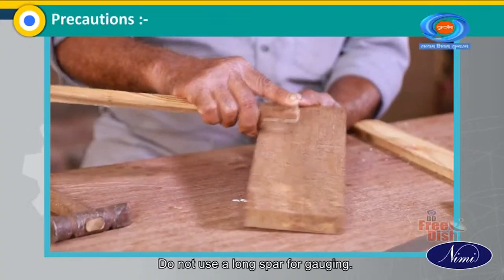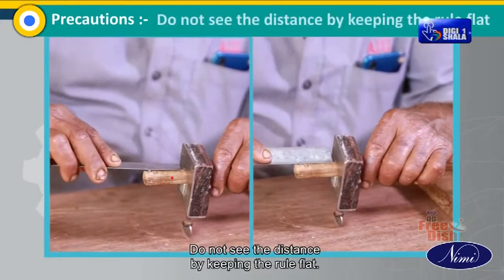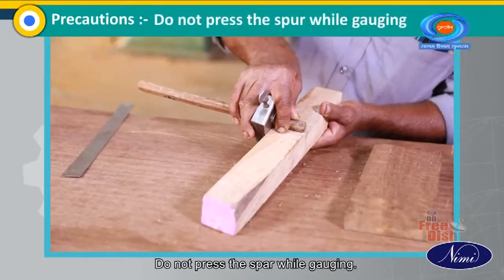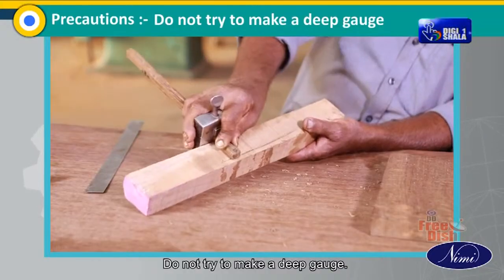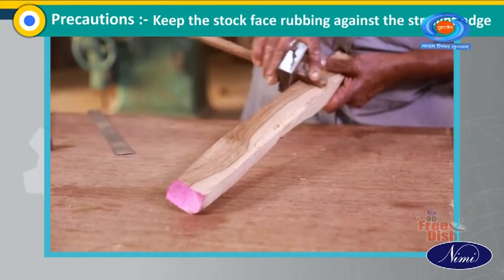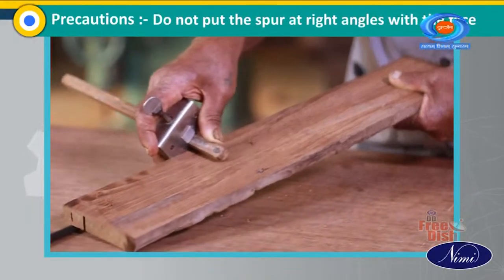Precautions: Do not use a long spur for gauging. Do not see the distance by keeping the rule flat. Do not press the spur while gauging. Do not try to make a deep gauge. Keep the stock face rubbing against the straight edge. Do not put the spur at right angles with the face.